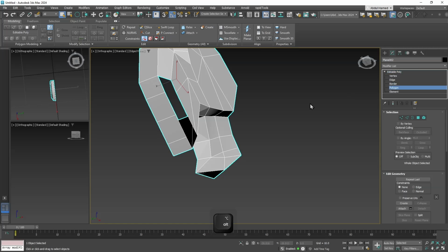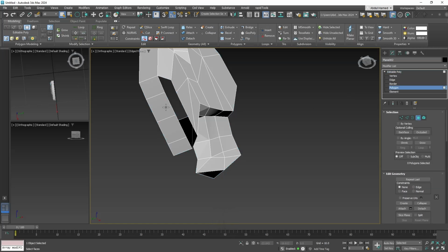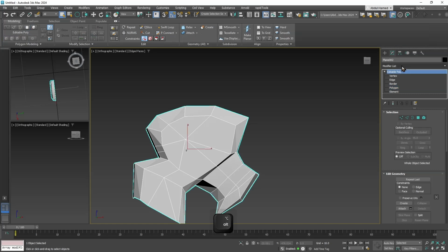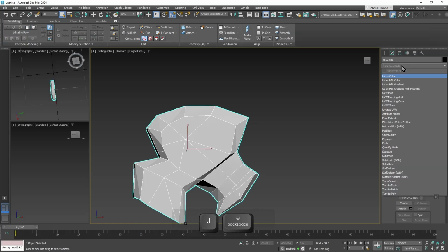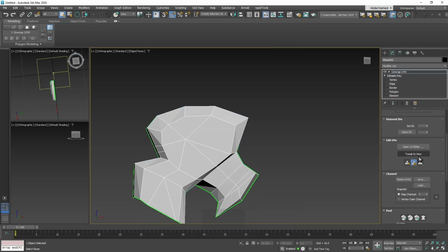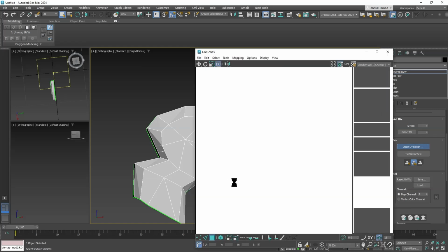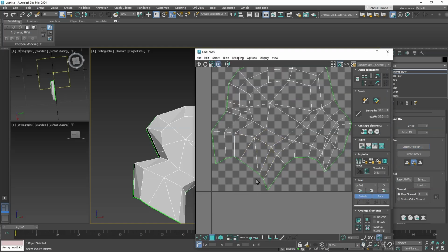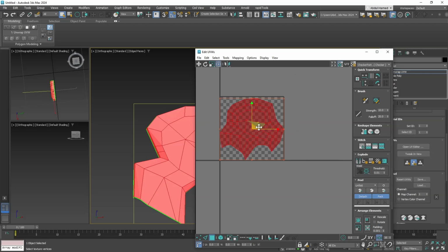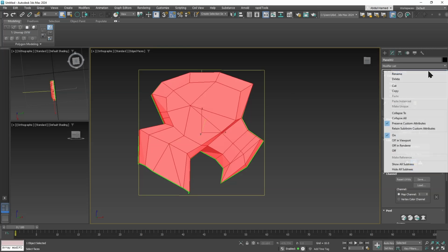So we're seeing, that's why we saw a hole within the UV. So if you select that, just delete that, and then let's open the UV editor. And now it has been fixed. So there used to be a bridge here, and now it's removed. So let's select the whole thing and let's offset it somewhere else, and let's collapse all.